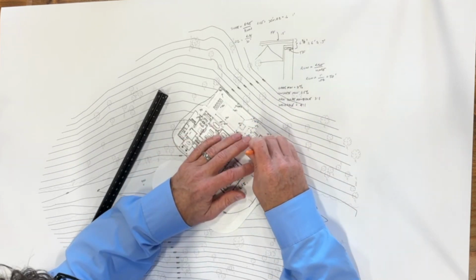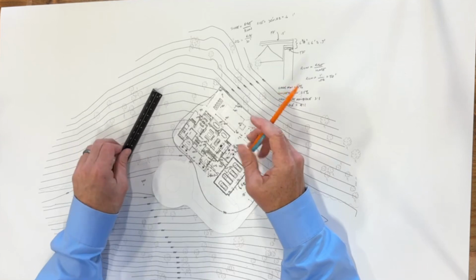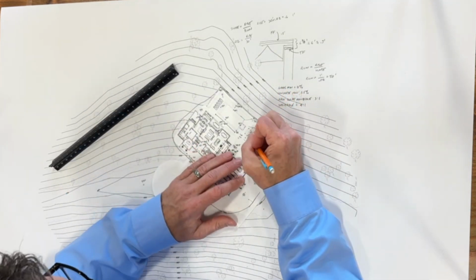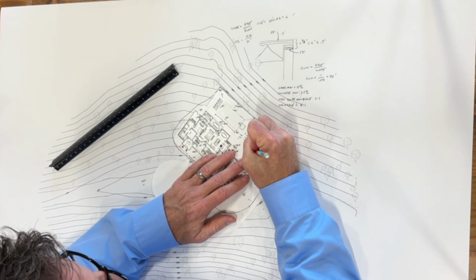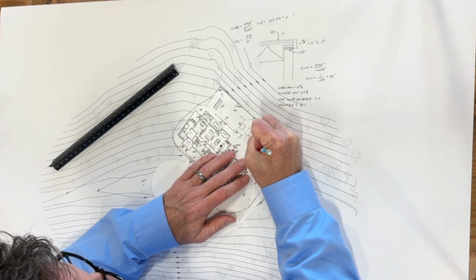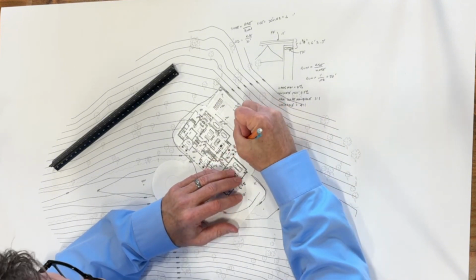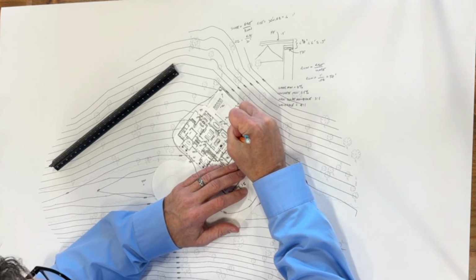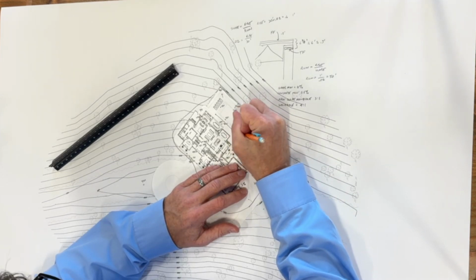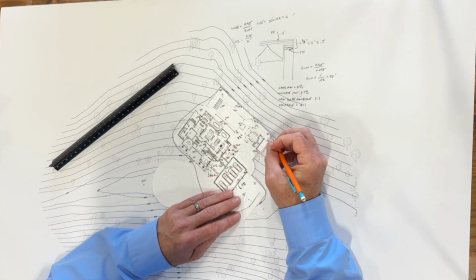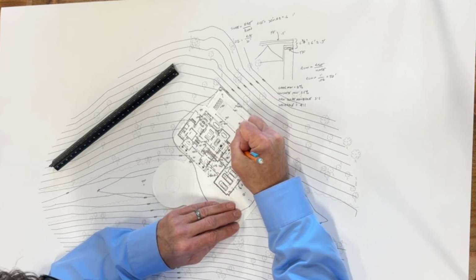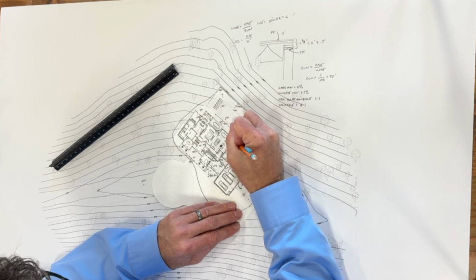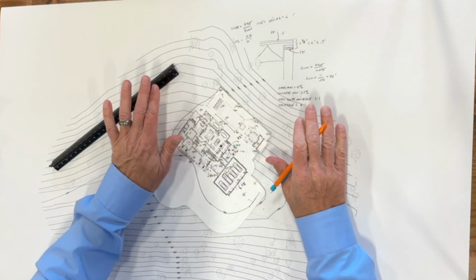So that means we probably got to lower this guy a little bit, because that is more than 20, that's 35 feet. So I really want to make this here a 939.5 to do a 1 foot drop. So I want to make sure the water gets out of here. So now what will happen is this just went from 2% to probably 3% as it goes to this 939.5. But now the water off of this patio is going to run like this. This is going to come down and go like this. So now I got everything going away.